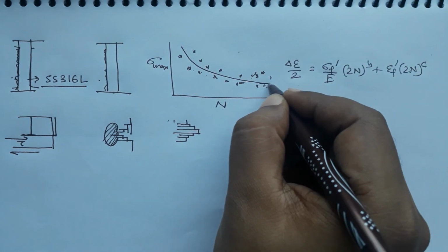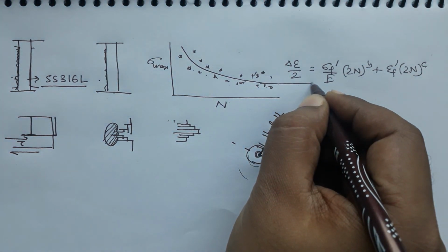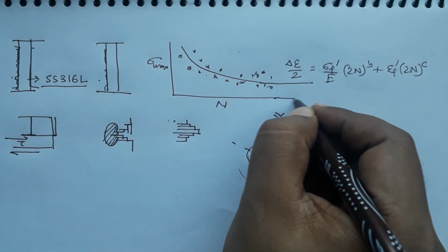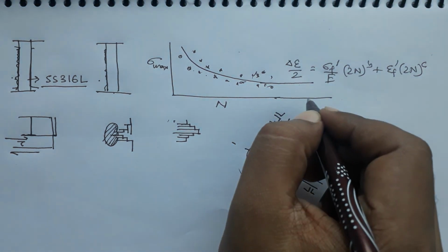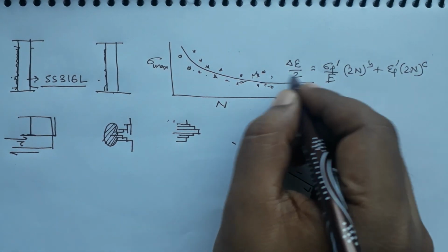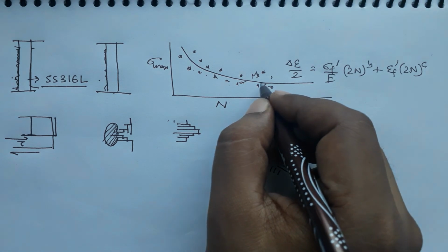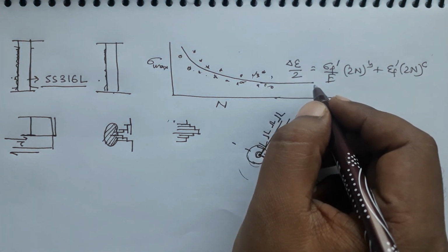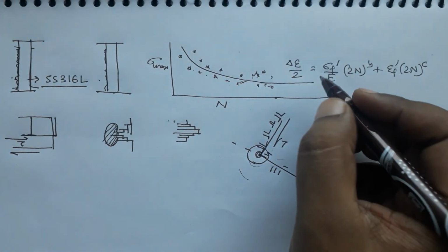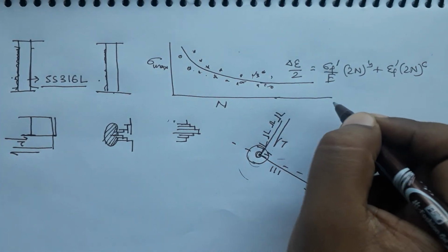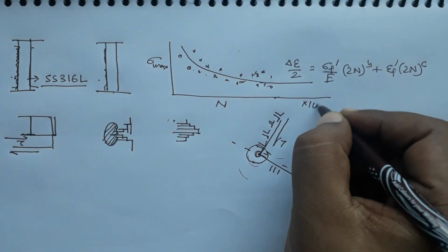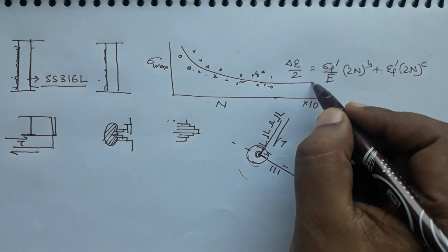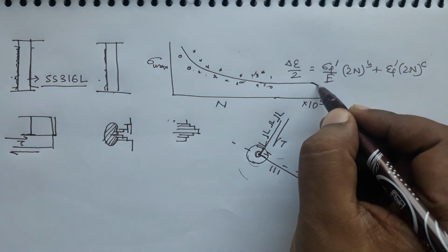So this curve becomes constant, meaning that you apply an infinite number of cycles and the material will not break. Research has been done for these materials also, where it appears that the material has an infinite number of cycles. So they become immortals. But after doing the fatigue cycle for more than 10 to the power 9 cycles, it was found that they also fail and this limit starts decreasing.